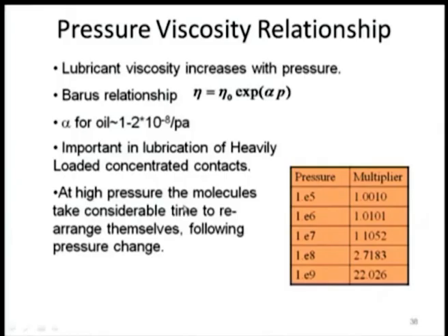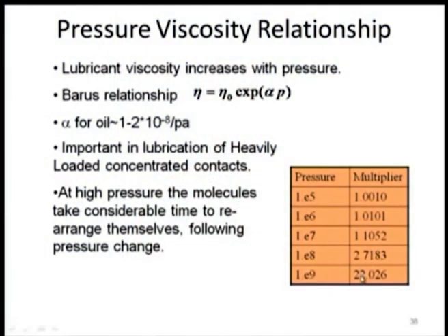And one problem comes. Even at high pressure, it will take some time to rearrange the molecules. It will not be spontaneous, it will not happen in 1 nanosecond. It may take a few milliseconds to a second to reach that equilibrium. That is why the effect may not be as dominating as what we are showing. Take the example of a rolling element bearing. It may take hardly 1 second or less than 1 second in a concentrated contact, and after that the ball or rolling element goes out of the contact. So, we will not be able to reach this full effect.